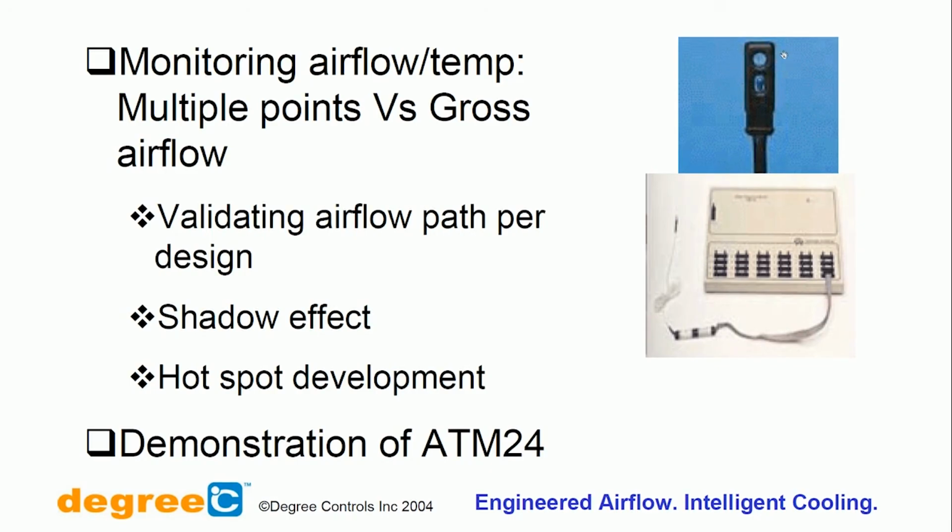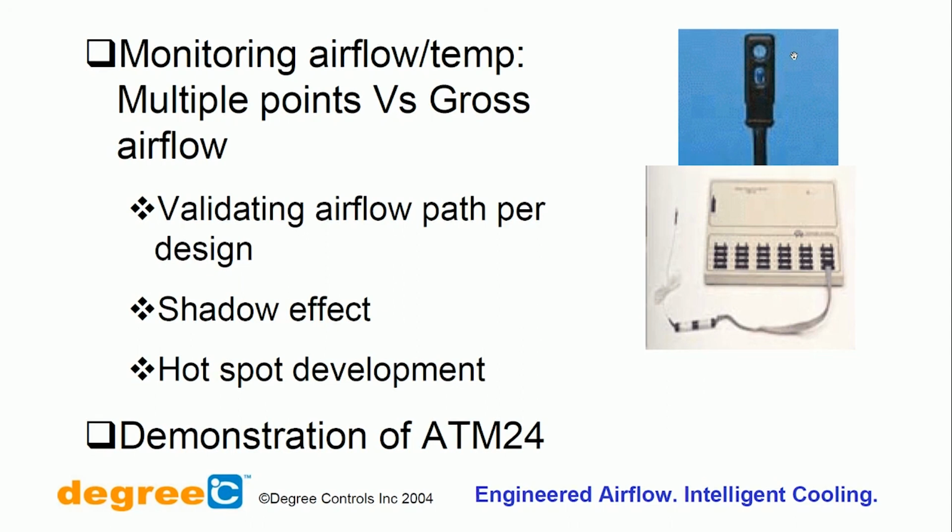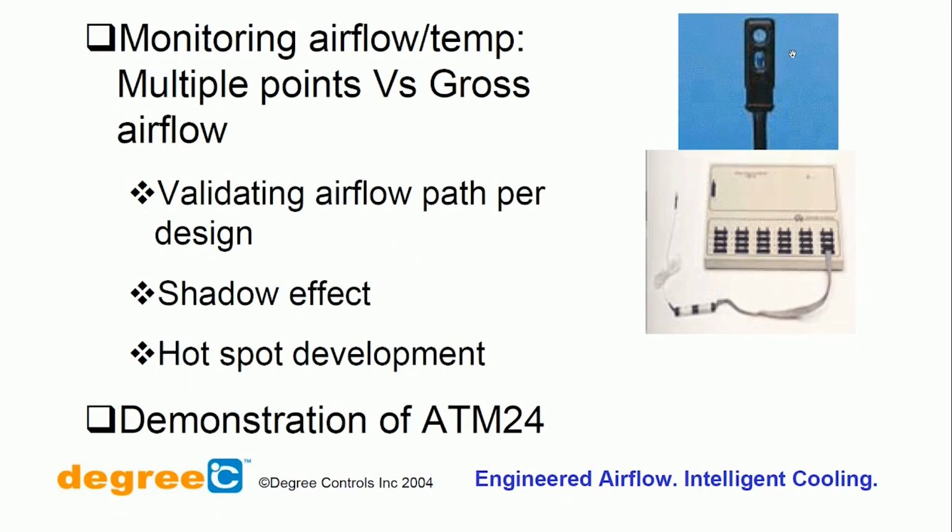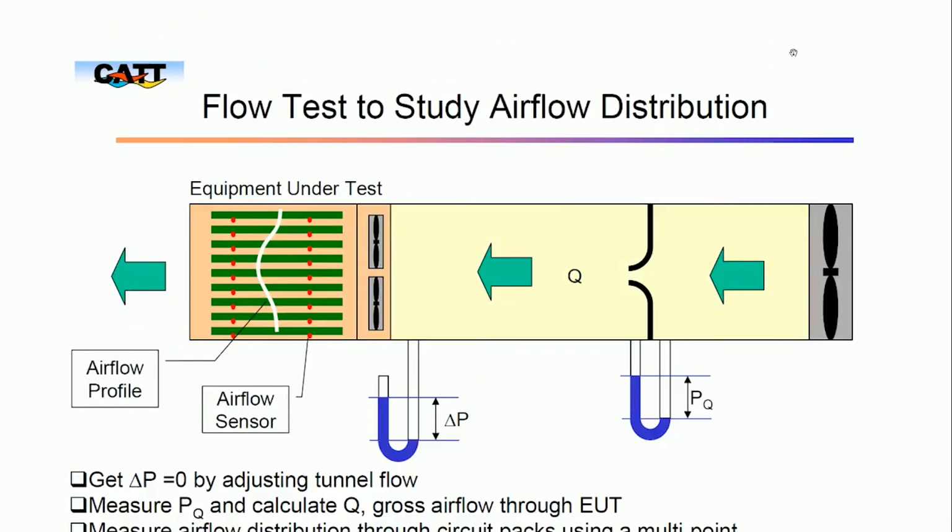a small turbine. So both types are there. There is a hot wire anemometer and an actual anemometer where there is a rotor which is turning. I can't make out whether it is a hot wire anemometer or a simpler turbine anemometer. Hot wire is a little sensitive to external factors, and extremely sensitive to temperature, and a regular turbine type anemometer has a beautiful thing.